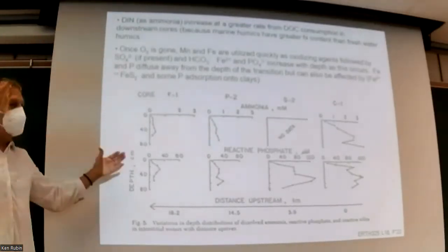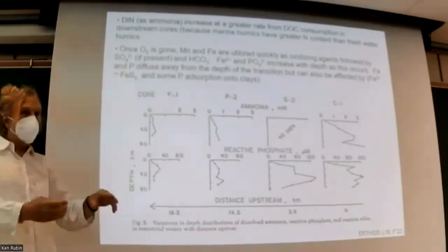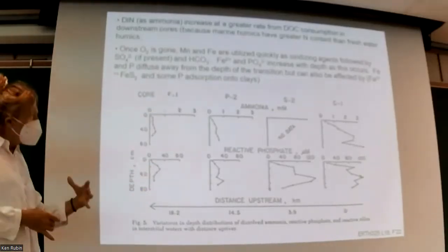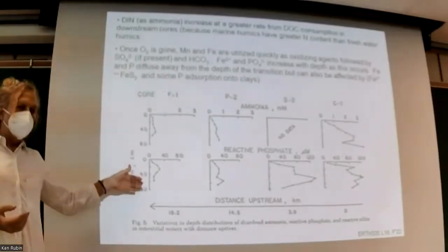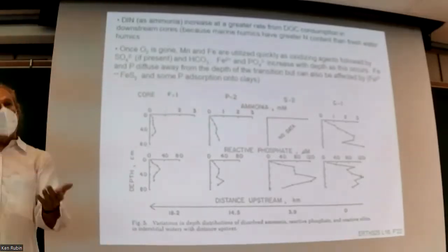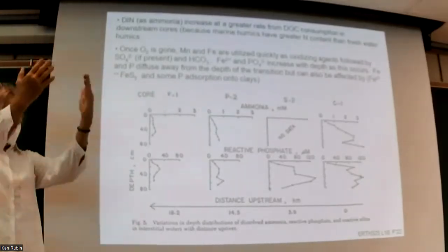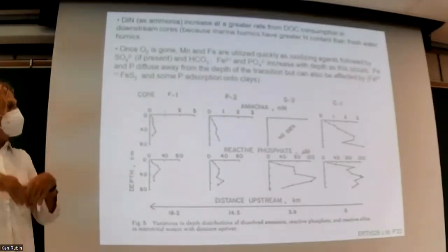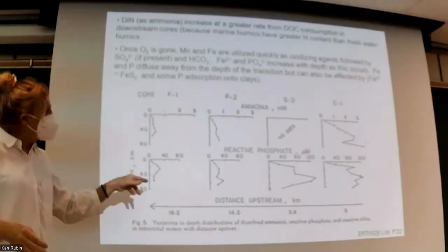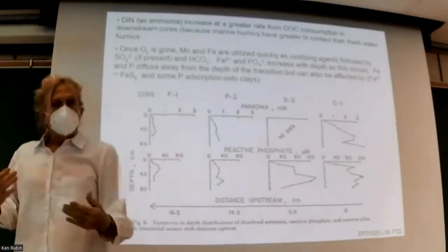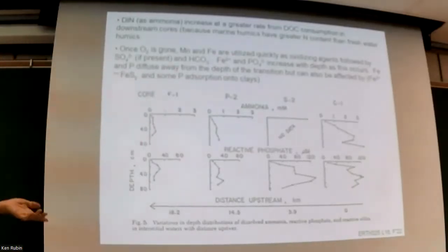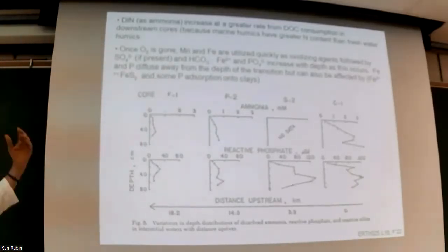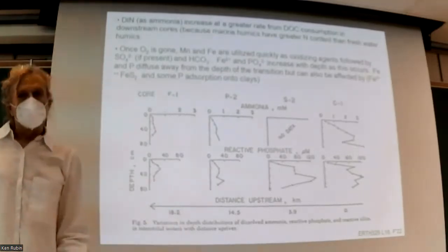Well, if we go into reducing conditions and we have phosphorus being liberated by our organic matter being decomposed and sticks onto particles of iron, and all of a sudden we get far enough down the redox ladder that the iron particles get decomposed, and because it turned from iron 3 into iron 2, then the phosphorus is going to get liberated. So phosphorus concentration will go up simply because the thing it was sticking to in the particles is now not a particle anymore, and so the concentration in the water will increase.